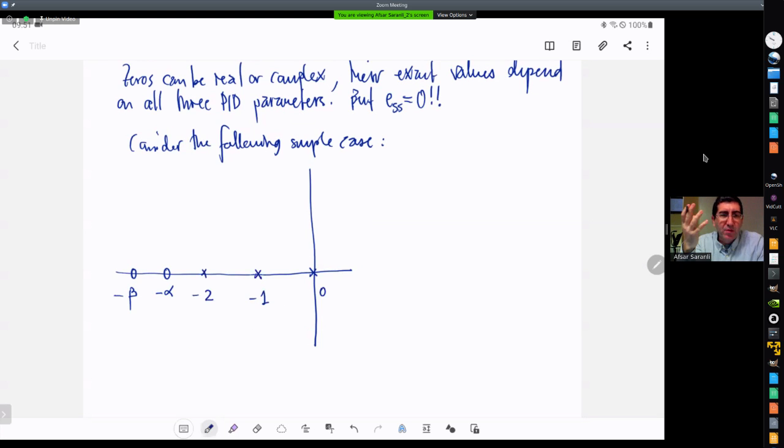At this point you have a feeling that it's often advantageous to put the zeros in the stable side of the S-plane, and even further left than any existing poles, because those zeros attract the branches of the root locus, eventually some of the branches will converge to these zeros, and that's a good thing, because any closed loop poles far from the j omega axis make a relatively more stable system.